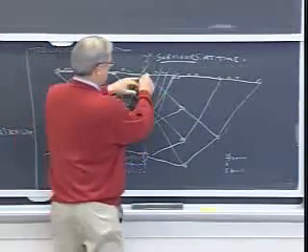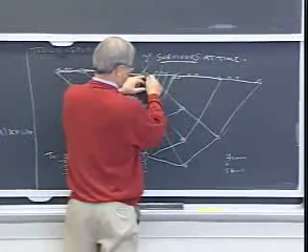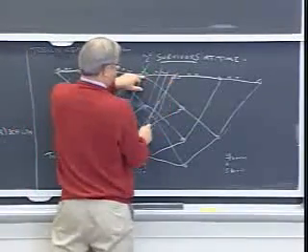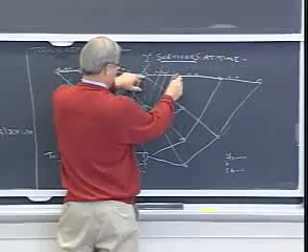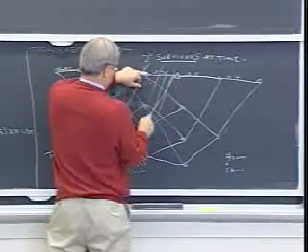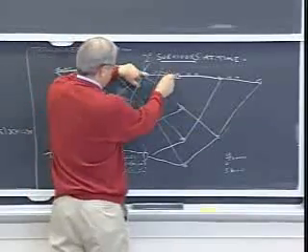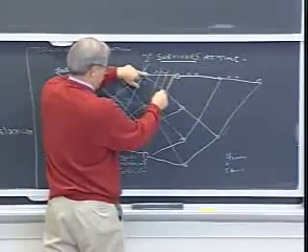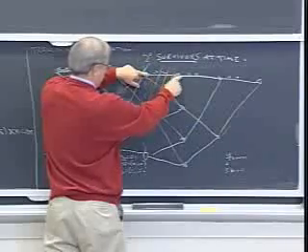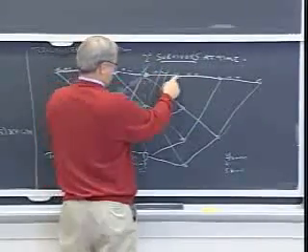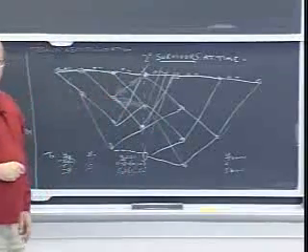Now, to proceed, the recursion is to proceed 1 time unit ahead, to add the incremental costs. Say, to make a decision here, I need to add the incremental costs to the 2 survivors that were here and here. So I add an incremental cost according to what these branches are labeled with, and now I find the best of these 2 possibilities to get to this node.